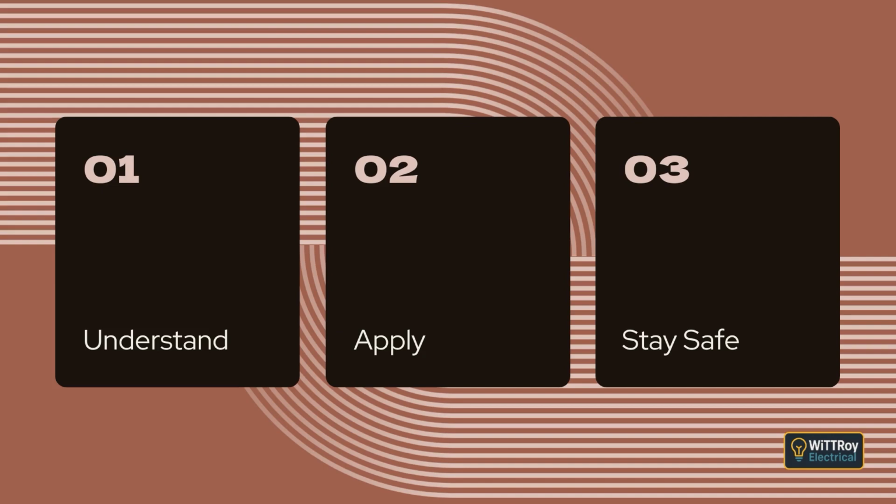Clause 3.7.2.3.2 Crimp joints. Conductors joined by crimping must use the correct type of crimping tool and the correct components approved by the manufacturer. When a crimp is correctly made, it forms a permanent and secure mechanical and electrical joint.